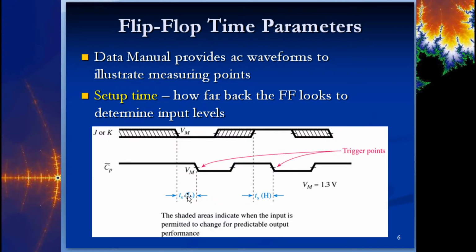Sometimes the setup times are different. You may have one for if it's going from high to low or low to high. But anyway, it looks back every time you have a trigger point for your clock, high to low or low to high, whatever it is. This one is a high to low. So those are my trigger points.